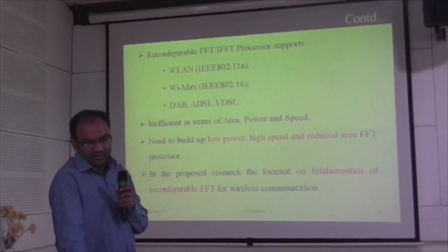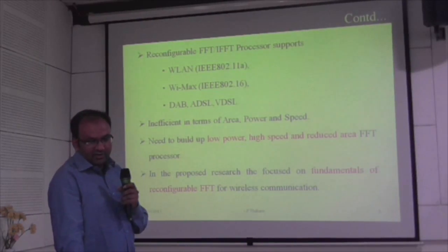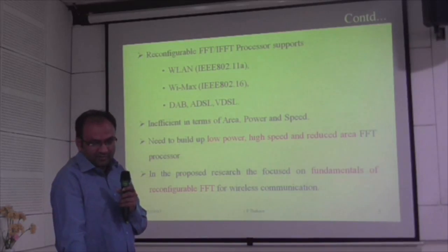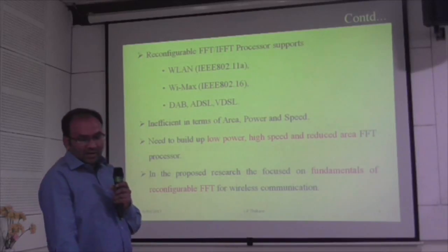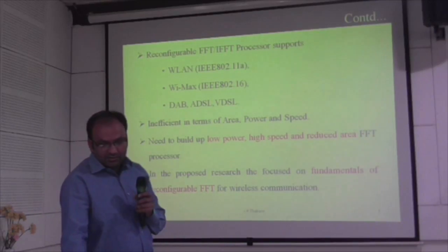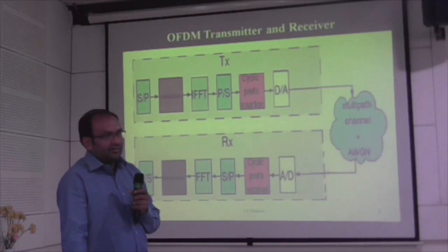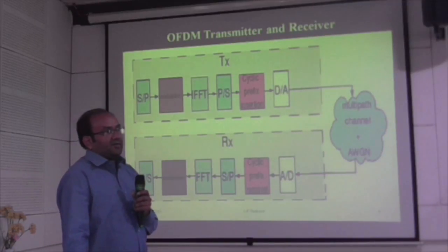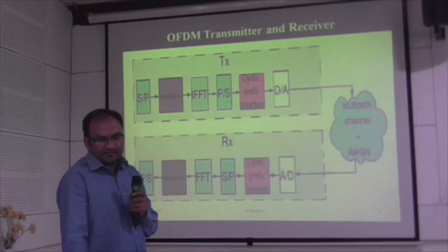So in this research work, I propose the fundamentals of a reconfigurable FFT processor to reduce the power, enhance the speed, and reduce the area. This is the block diagram of the OFDM transmitter. The IFFT is used on the transmitter side and the FFT on the receiver side for modulation and demodulation.